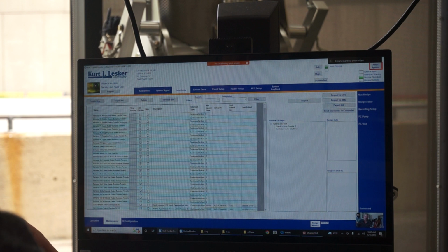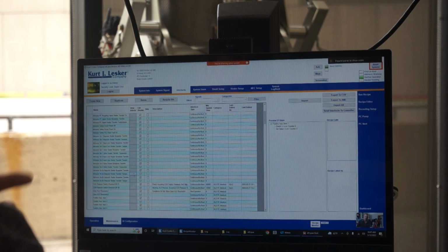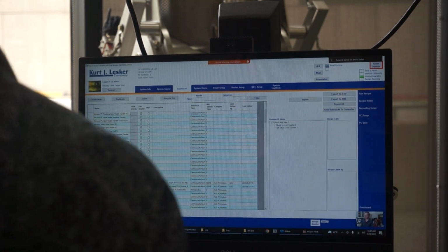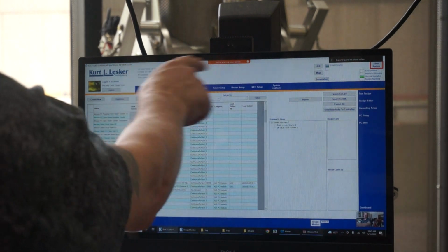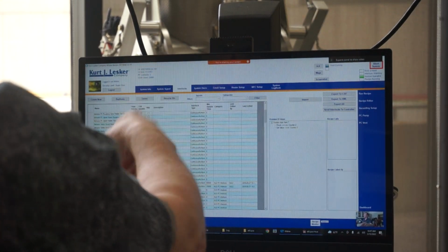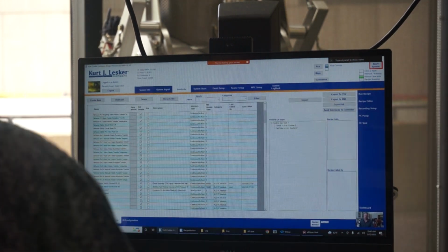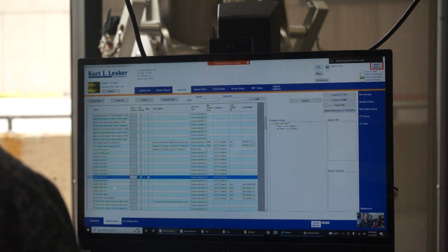Behaviors and interlocks. The difference between a behavior and an interlock: a behavior automatically happens. So we manipulate it, so if this is a condition to automatically do that. With the behavior, you won't get any prompt. The interlocks are set to give you a prompt. And even though that condition might clear, that'll stay up here until you acknowledge it.